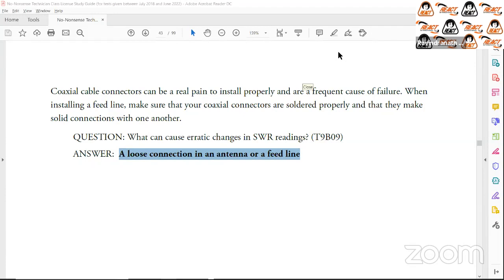But like everything else, just like electrical cable in your house, you should check the insulation and change it out from time to time. All right, so no cable lasts forever. But once you select the right type of UV rated cable, you will get the maximum life out of it, but you will eventually need to change that cable as it deteriorates in the sun. Good question there, Anthony.